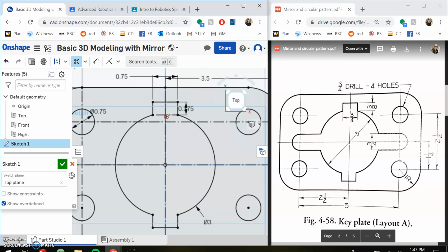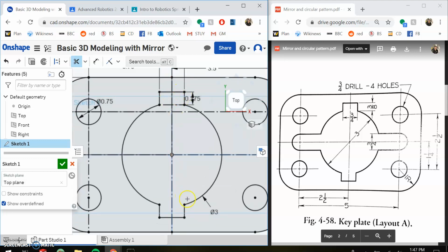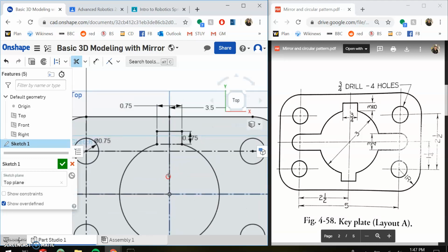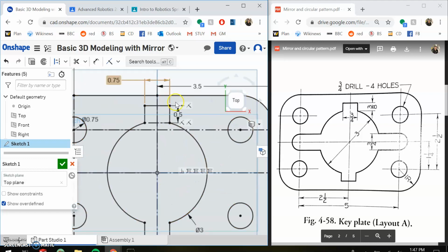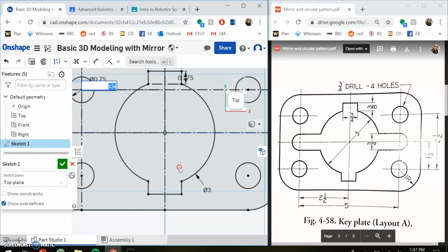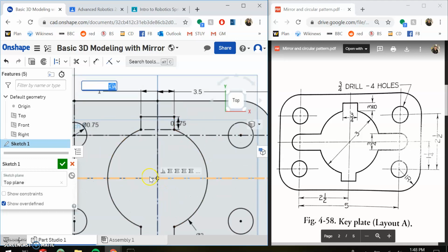Okay, this section is now complete at the right size, and if I want to modify anything, I can change how far this sticks out. If I want to make it 0.5, it'll stick out a little further. It'll change on the other side. Back to 3/8, I can change this distance to be 1 inch, and we'll just spread out further. So it's really nice because it does it everywhere. But let's put it back to what it's supposed to be, which is 0.75.